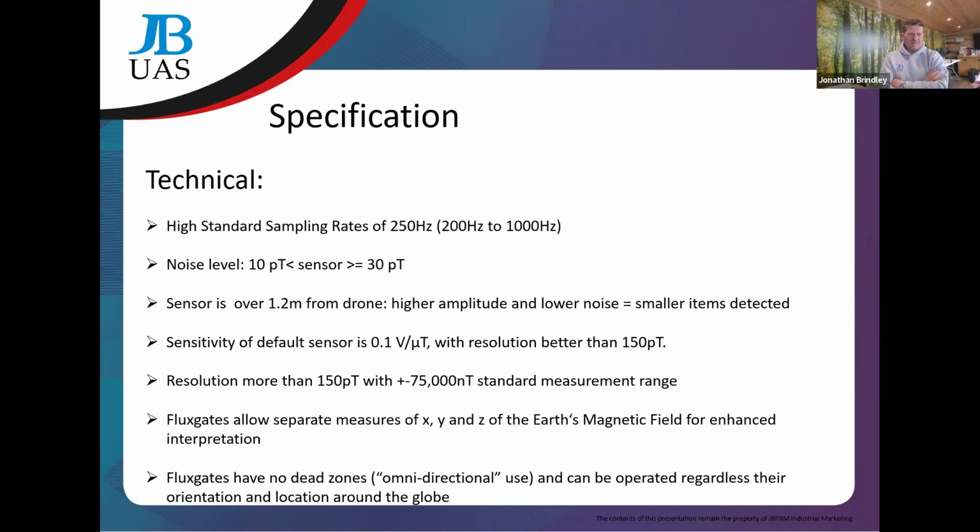Noise level. Remember, this is just the sensor. When you put the sensor into a system, into its casing next to the drone with all the other factors, it's not the full picture. But certainly from a technical perspective of the sensor itself, 10 picotesla is kind of the noise level.